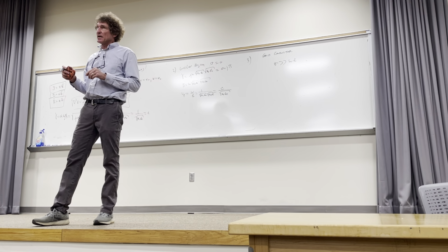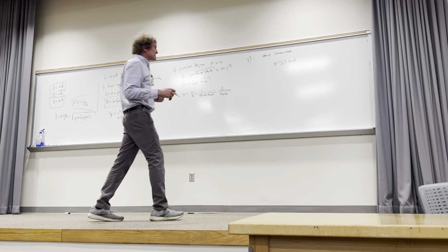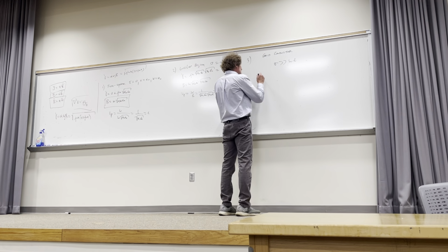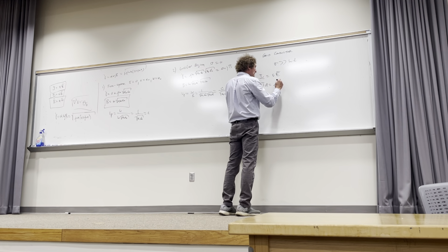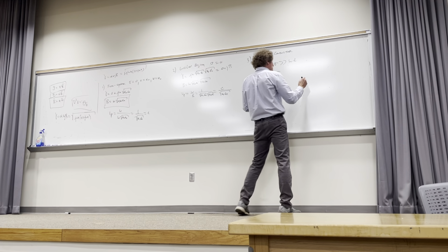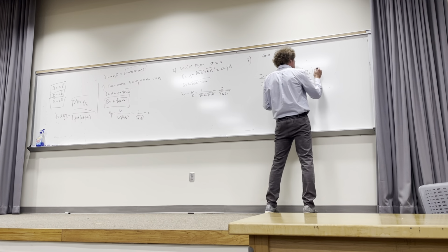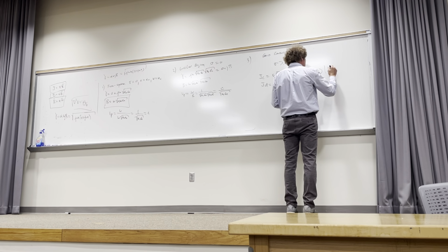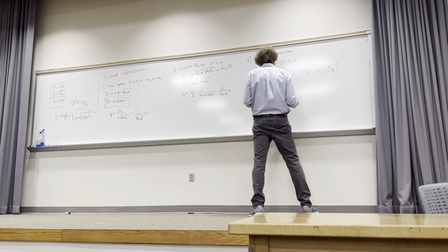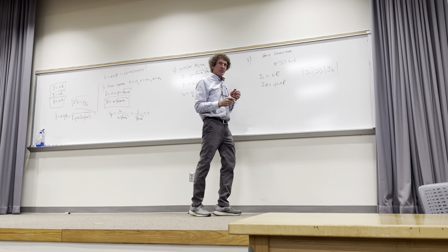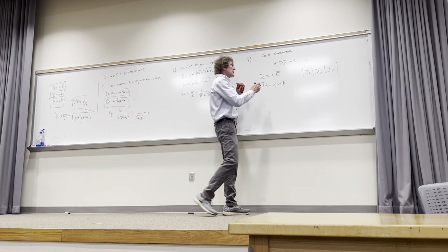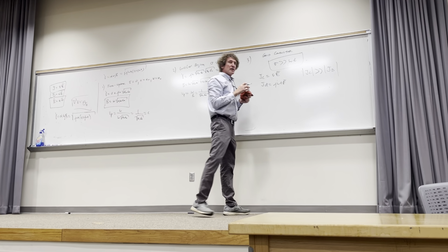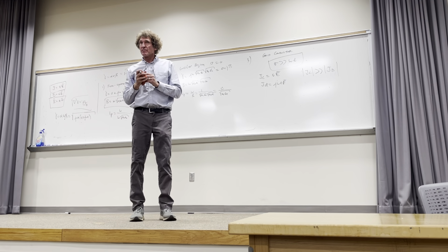And conduction current is sigma E. So J conduction is equal to sigma E, and J displacement is equal to j omega epsilon E. So whenever the magnitude of J conduction is much, much greater than the magnitude of J displacement, you have a good conductor, for a given E field. Microscopically, that's what it means.